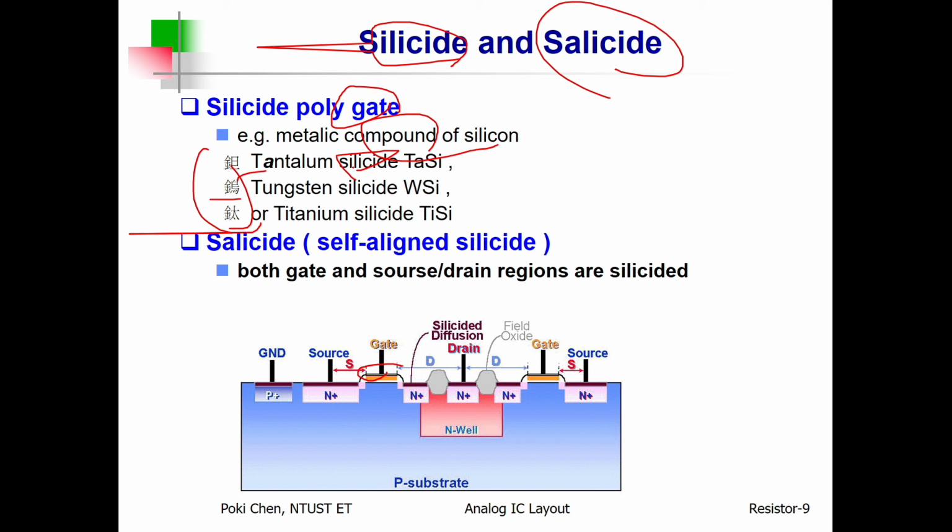I mean, the main body of the gate and such kind of silicization, they are fabricated in parallel. So it means the overall resistance will be substantially reduced with such kind of silicization. Anyway, if you only speed up the operation of gate, it is not sufficient. We can also speed up the operation of your source and drain. But how? You need to do the same thing, right?